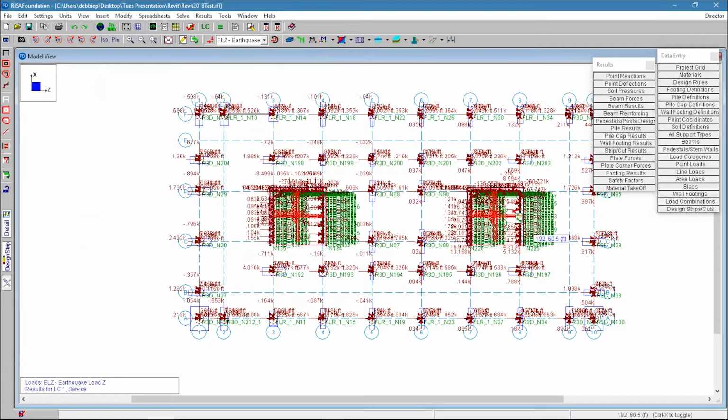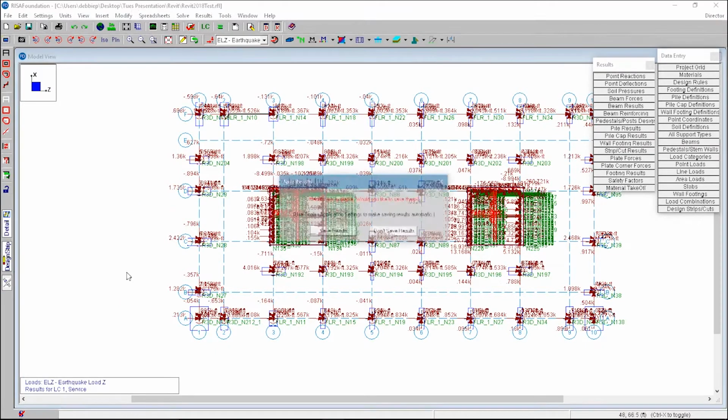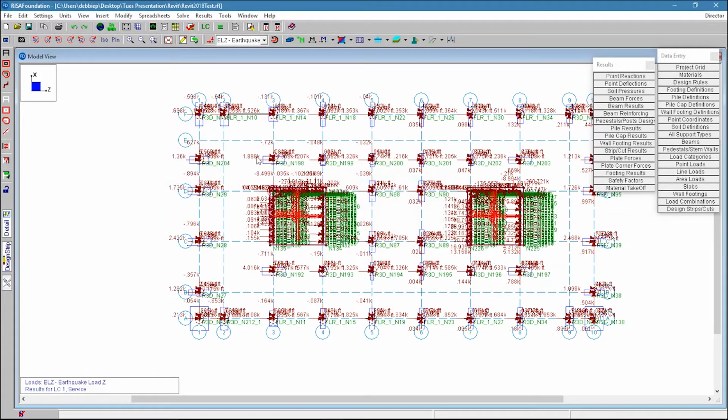So the big trick on Revit here is not hard, but what you want to do is save your model. So save results. That's what's happening. This results here, why that's important is these footings are placed in the model but not sized until the solution is present. So you have to have that solution present, and then you're done. You can close your model and use the floor. And that's all it takes.